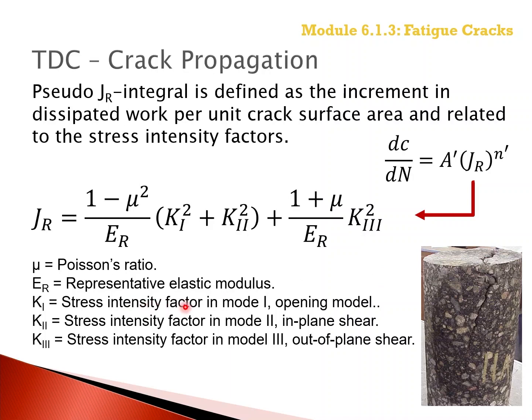As displayed on the core, the crack depth is not restricted to the upper 1.5 inches of the asphalt layer. As mentioned previously, some industry experts believe and have reported that the top-down crack depth will be restricted to the upper 1.5 inches.